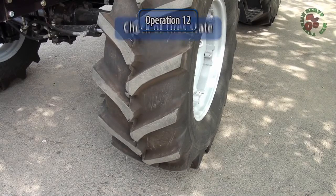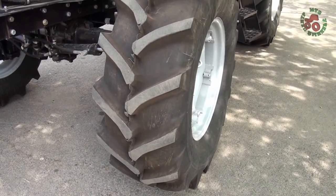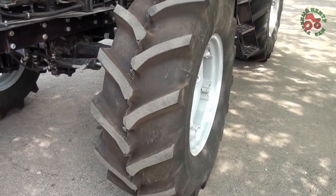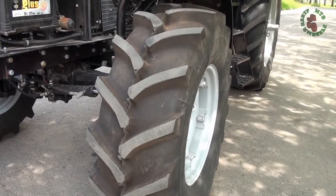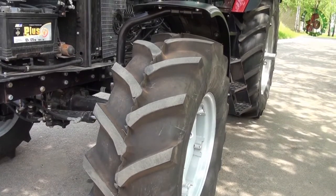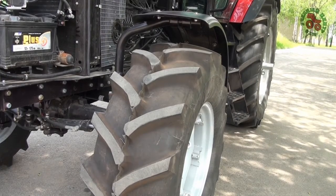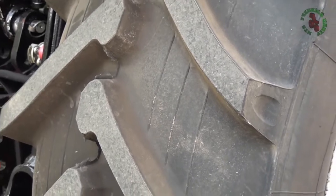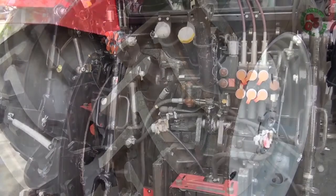Operation 12. Check of tire state. Carry out inspection of outside appearance and conditions of the tires in order to detect faults or objects getting stuck in the tires. If necessary, clear the tires of the foreign objects. In case the tires have defects going up to the tire fabric or cracks going through the whole tire thickness, dismount the tire and send it to the special repair workshop for treating. If the tires have defects beyond repair, replace the tire. Defective tires shall be sent for recycling.